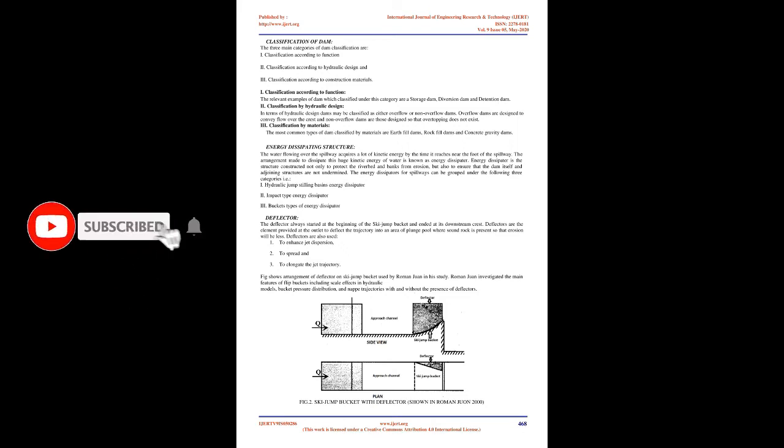2. Classification by hydraulic design. In terms of hydraulic design, dams may be classified as either overflow or non-overflow dams. Overflow dams are designed to convey flow over the crest, and non-overflow dams are those designed so that overtopping does not exist. 3. Classification by materials. The most common types of dam classified by materials are earth-fill dams, rock-fill dams, and concrete gravity dams.